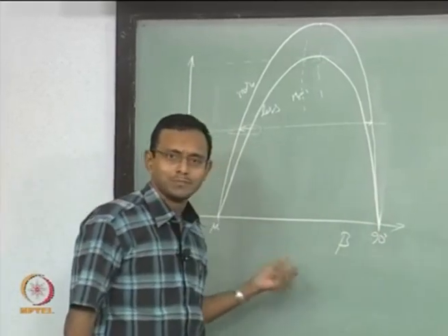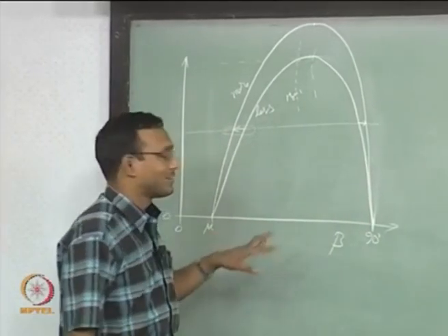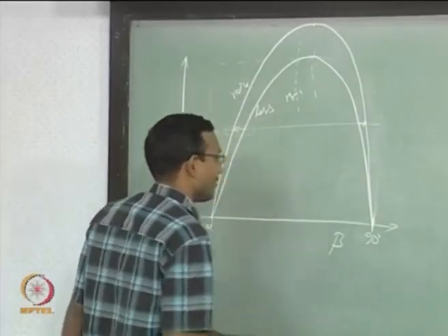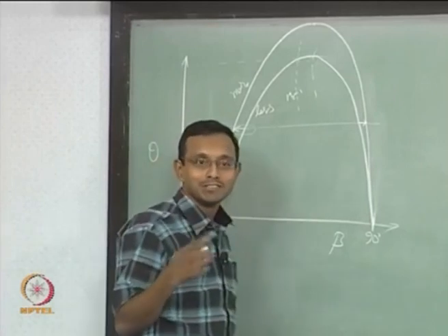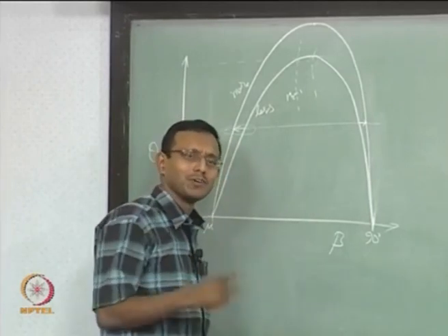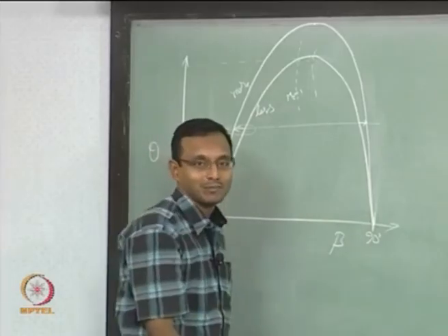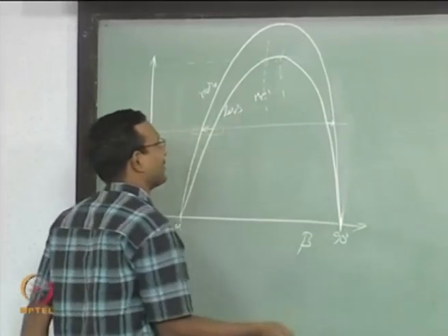Normal shock again is just a perpendicular change, and there is no difference in beta really, there cannot be any difference, beta is 90 degrees, normal is normal. Of course, there will be a difference in P2 by P1 values, slightly, we won't worry about it. You know that the P2 by P1 formula has gamma in it, so if I change gamma, gamma will have an effect on P2 by P1. Let us not worry about that part also.